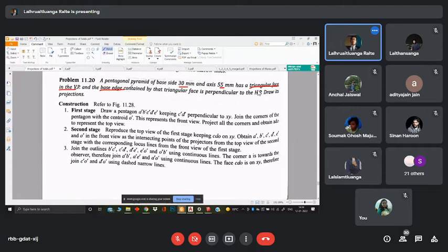I'll repeat that each pyramid will have a triangular face. It can be a square pyramid, a triangular pyramid, hexagonal, pentagonal, heptagonal. All of those will have a triangular face. And if that face is lying in one of the reference planes, then make sure that you are rotating your solid with that particular edge as the anchor point.